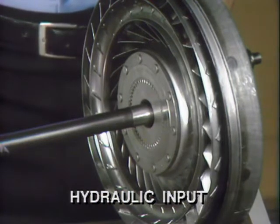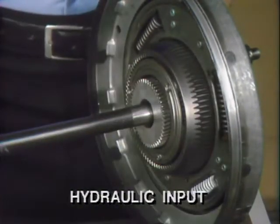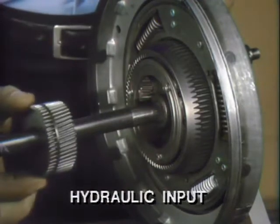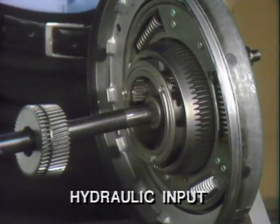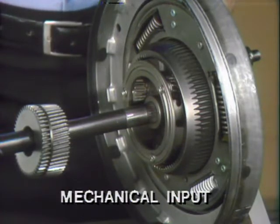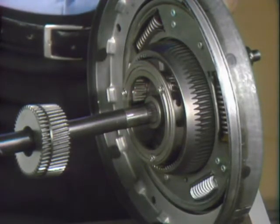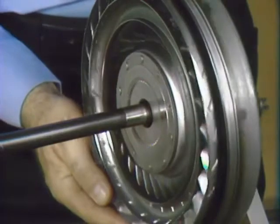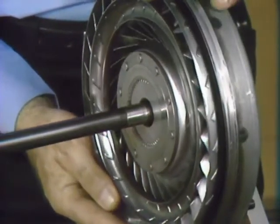Now, the hydraulic input goes the other way, from the turbine to the sun gear, to the planet pinions, to the pinion carrier, to the intermediate shaft, and into the main gear train. At the same time, the mechanical input is through the cover, damper, ring gear, pinions, planet carrier, and intermediate shaft, as we saw earlier. The splitter planetary unit combines the mechanical and hydraulic into a single split torque input through the intermediate shaft.